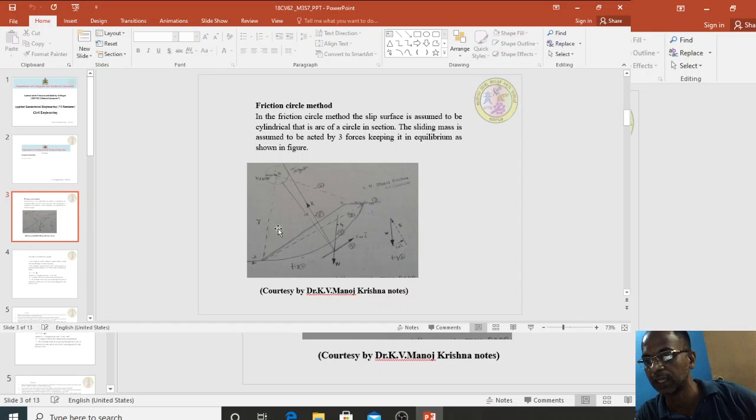Now, the curvilinear triangle OAD is half into base into height. The base is the curvilinear length L, and the height is R. Minus the straight line triangle, meaning half into base AD, the long chord, into the mid-ordinate distance, which I consider as Y. That gives half into base into height, plus half into base AD into BD.